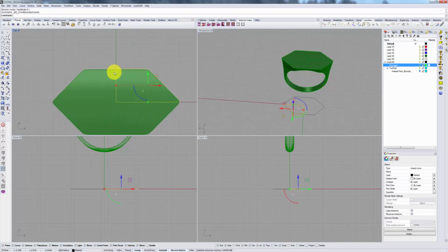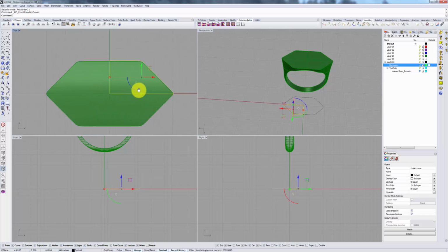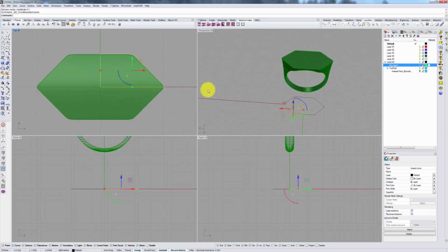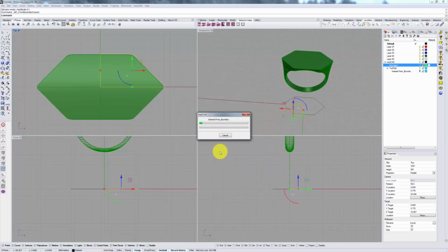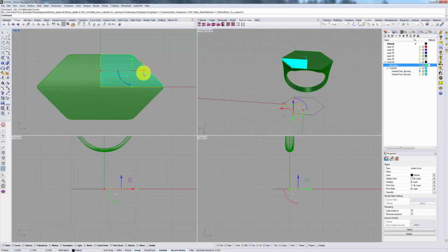So I took that boundary curve and just segmented it into 4 and selected just this 1/4. And I'm going to do curves from boundary, or rather toolpath from boundary curve calculation. So because we have the X and Y kind of quadruple symmetry here, there's really no reason to calculate this whole surface. We can do one quadrant and then mirror it over every which way.